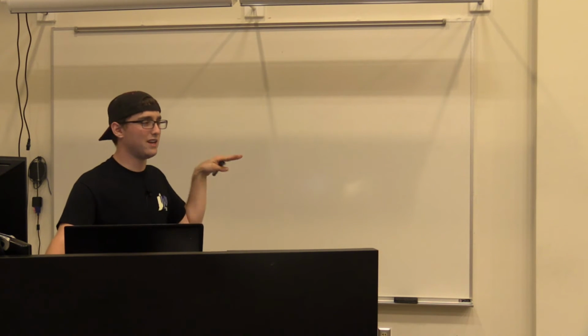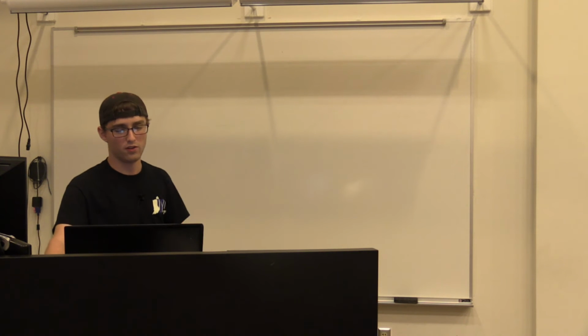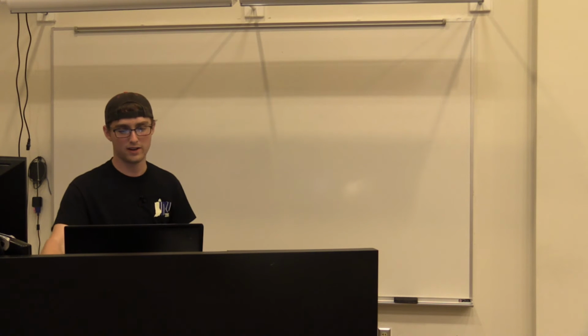Pretty simple. So if you go right up here, you'll see these two bars, right? The bar on the left, that's your material bar. So you can choose whatever you want. This is going to impact things like stress analyses, and it'll change your default part look. So if I choose polycarbonate, you can see it changes the view. It also changes the material. So if I went into a stress analysis and compared aluminum and polycarbonate with the same thing, it's going to change those factors.